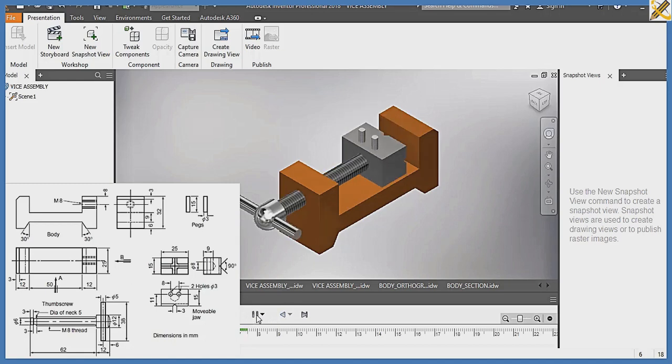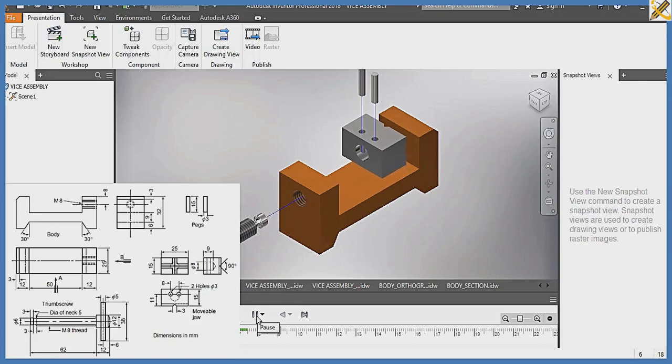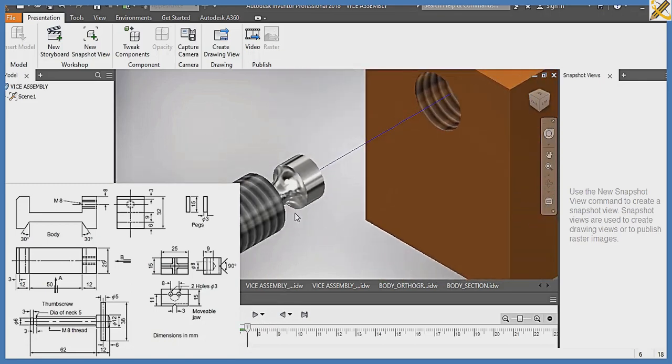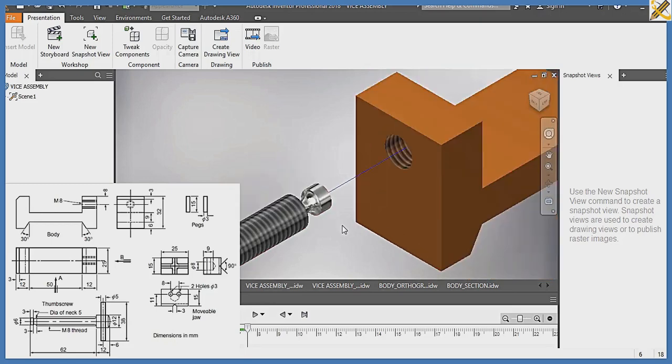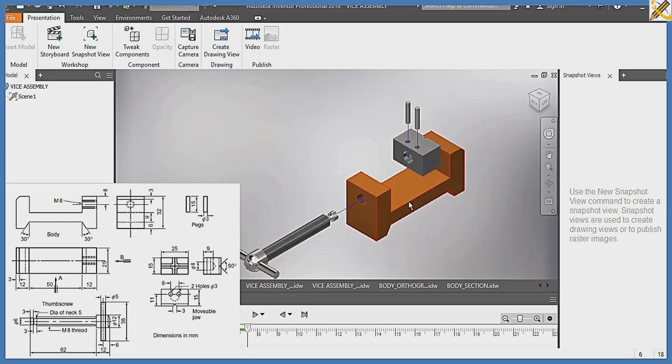So if we are to disengage it, the pin comes out first. All right, before this can come out. And the reason why the pin is going to come out first is this. That pin is the one holding, the pin is sitting right here and right here. So it's holding this one in place inside this particular portion here. So that is why the pin needs to come out first, then this out, then this. Okay, so that is that about that.